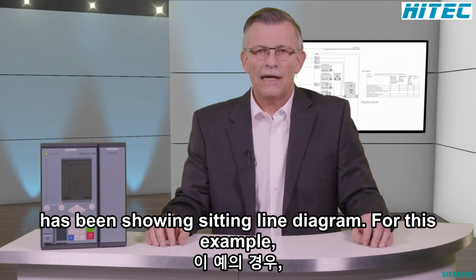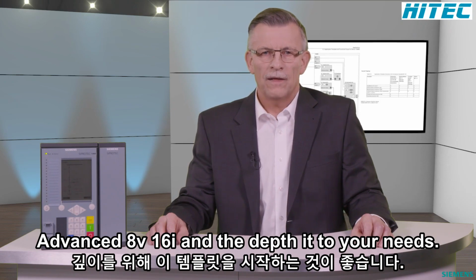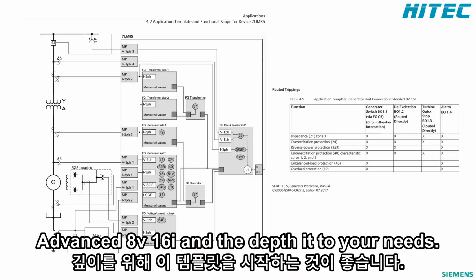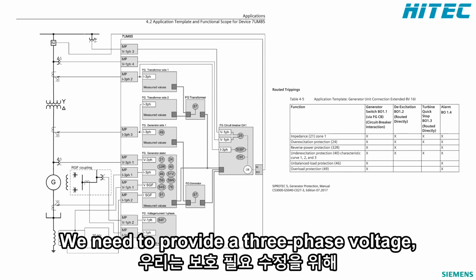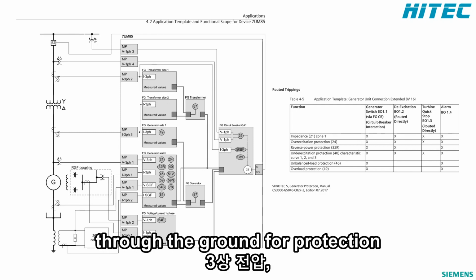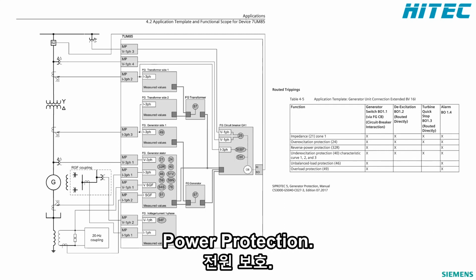For this example, I recommend you start with template 4, generator unit connection advanced, 8V, 16I, and adapt it to your needs. Which modifications are necessary? We have to add additional current transformers. We need to provide a 3-phase voltage transformer on the high voltage side. The rotor ground fault protection needs modification. We need to add a function group for the reverse power protection.